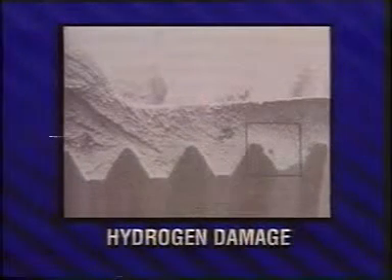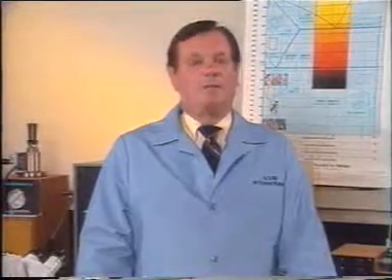Hard plating materials, such as chromium, are usually in a state of residual tensile stress after being deposited on the base metal. Cracks develop in the plating material. The cracks act as stress raisers, and if the cyclic stress amplitude is sufficient, the stress raisers may produce cracking in the base metal.